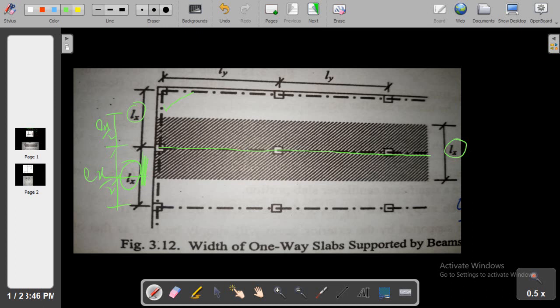So it is simple to calculate the loading over a rectangular beam in the case of a one-way slab system. Remember, let's say we have a cantilever portion on this side. In that case the tributary area will be extended. This area will also act over the beam.